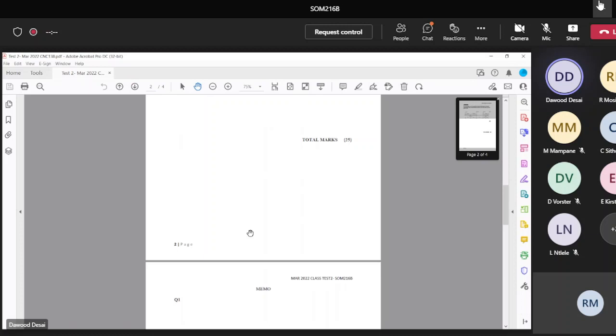Okay, you can do any one first. You can see here's the calculation. You take the bending moment at the point in terms of x, the unknown distance. You equate it to 0. You must end up with a quadratic equation, ax squared plus bx plus c. So this is a very important part. This part here must end up with that equation. Then you use a calculator and you'll end up with 4.699, which is unrealistic, and you get the 2 roots, and 2.899 is the distance. The first one is 2.899.